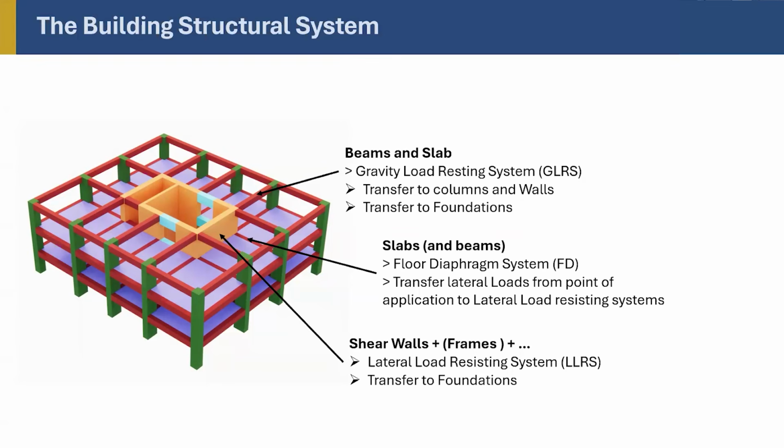This is a table, right? And these have two legs over there. And if I apply the load here, then this load must be transferred to those two legs through this slab in plane, right? Because I'm applying the load here, but it must be transferred to those two shear walls at the corner. So this slab must carry the load in plane. So this is the diaphragm effect. Because the mass of the slab is here, the force will be generated in the center, and it must be transferred to the lateral load resisting system. And then the eccentricity will come in. We will study a lot about mass and stiffness eccentricity and all that kind of stuff. And that is from the floor diaphragm.